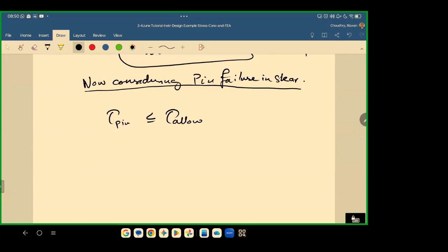Tresca criteria. Okay. Using Tresca criteria, assume, so basically if you use Tresca criteria, you can say that the tau yield is sigma yield over 2. Okay. Like I said, right now I've not explained the basis, but inshallah, in the next few lectures, we will go through the mathematical basis for this criteria as well.